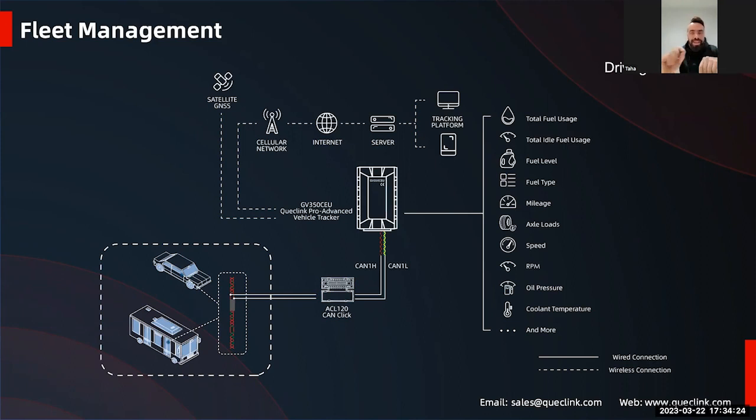Then from the LED of the CANbus, you can know if your device has been synchronized successfully or not. After rebooting the device, the LED of the CANbus needs to be flashing green. Otherwise, there are troubleshooting steps in the protocol where you can see what the problem is with the synchronization. Maybe your wire is not correct, maybe there is no ignition on, and so on.